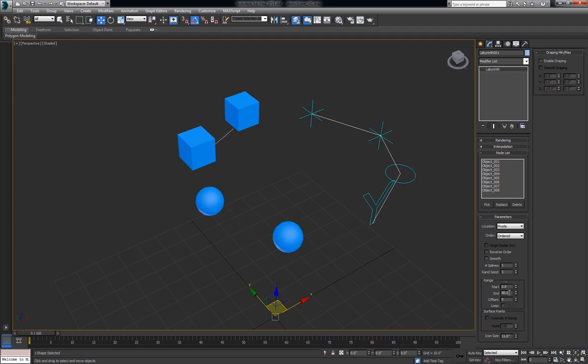Now I'll switch this back to 100 here. And if you turn off loop, what it does is when the spline hits the last point in the ordered list, we'll say, it won't go back around and continue through the points again. It just stops. Whereas if you have it on, you'll see it loop back around. So that effect is very cool and can be very helpful.